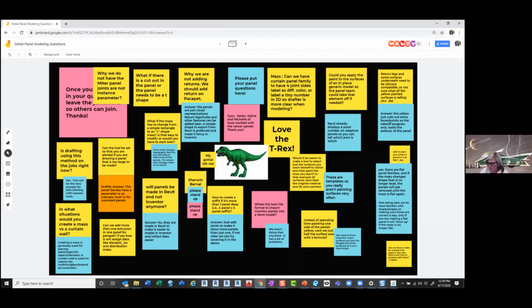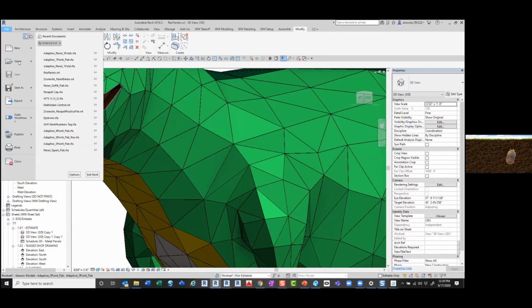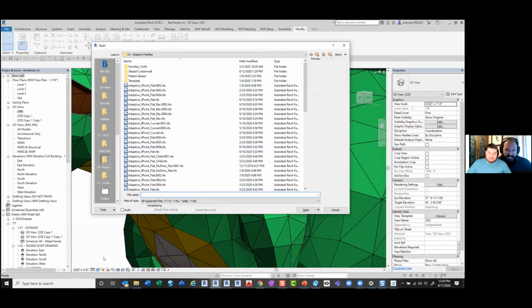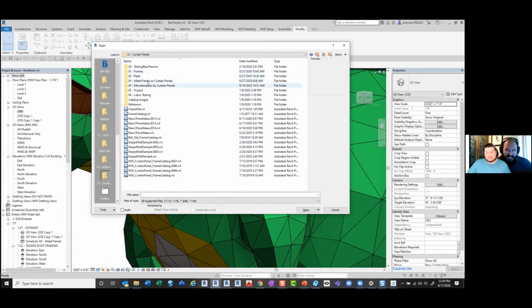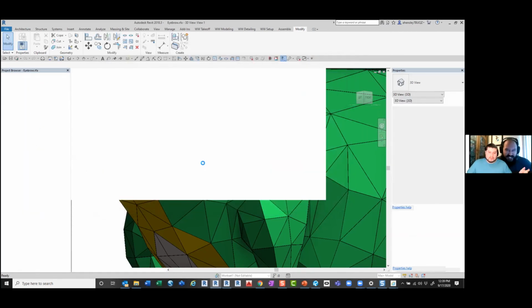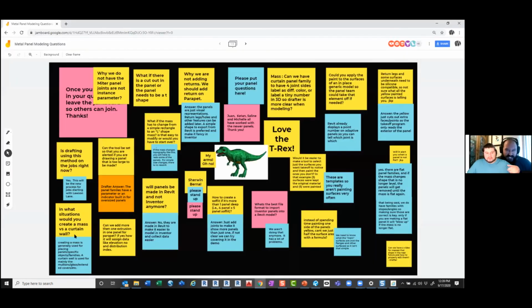Can we add more than one extrusion in one panel for parapet? Yes. So that goes back to the eyebrow. You can, but I don't encourage it. Yeah, Amy, I was going to say that it's pretty bad for the panel group. Because normally when there's a separate panel inside of a parapet, it's normally a clip. And so if it gets put inside the family, then it's run as a full length piece. And so now we have a bunch of stock length parts when we only need pieces.